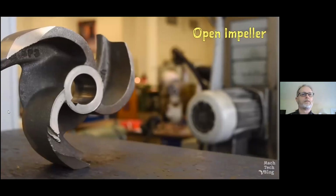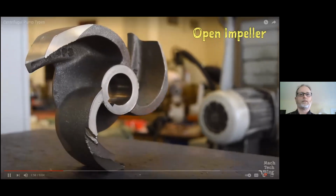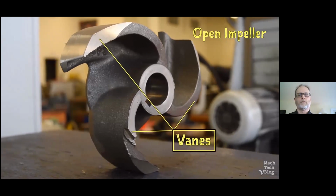The simplest impeller construction is the open impeller, which consists of nothing more than a few curved blade-like vanes equally spaced around a hub on the rotating pump shaft. Large, unrestricted fluid pathways allow this type of impeller to pump fluid containing mud, leaves, twigs, sand, sludge, spray paint caps, dead birds, you name it.